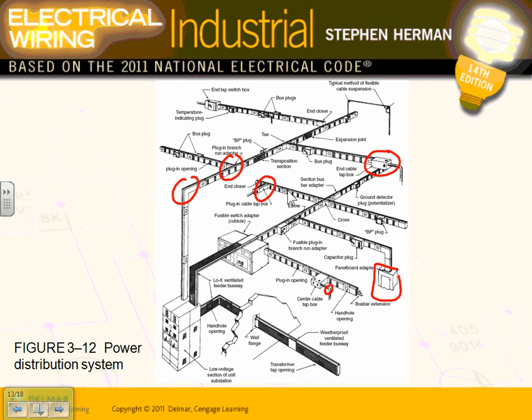This is my favorite, where you can bring a big chunk of power from point A to point B with busways. This could be, guys, 2,000 amp. So if this switchgear can give, I don't know what the size is, 2,000 amp, and this piece of equipment could be 2,000 amp. So instead of bringing 2,000 amp from switchgear to the switchboard with cables, they actually bring a 2,000 amp bus to bring all the power all together. No cables, no conduits, nothing. Any comments? Any questions?